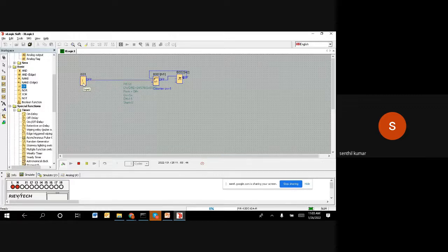Bottle 1, bottle 2, bottle 3, bottle 4. If I make bottle 5, the output becomes on. And once it becomes on, the OR gate will go here and it will become a 1. The 1 will come and reset and immediately go off. But maybe you may not be able to see it with your eyes because the execution is very fast. Let us do it now. Right. So actually what happened, you can see the count becomes 0. It got reset. Technically it became on, and the on has gone through this OR gate, and the OR gate has given a reset and it has gone.